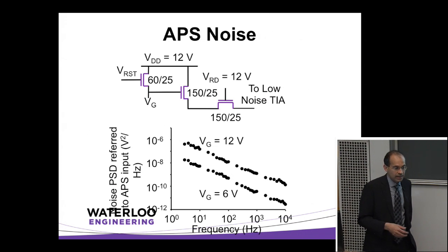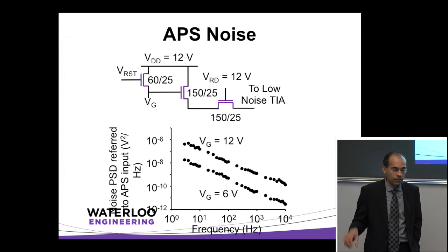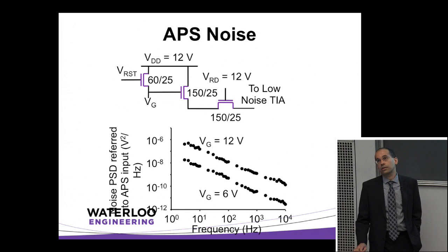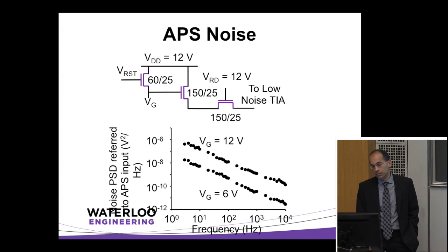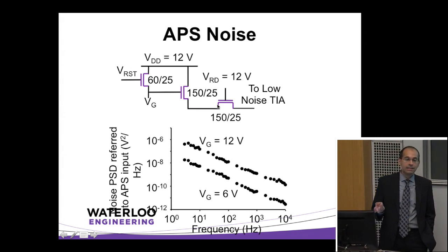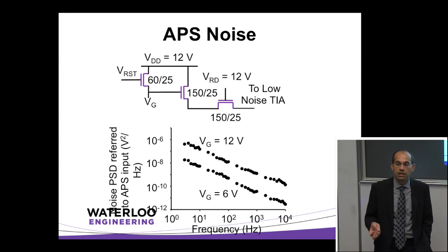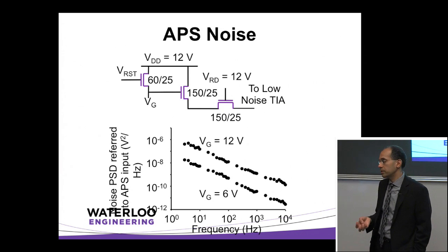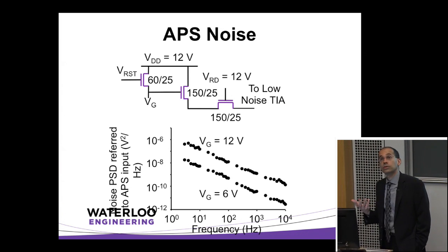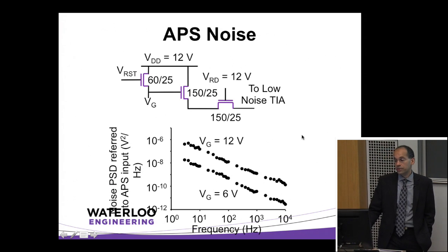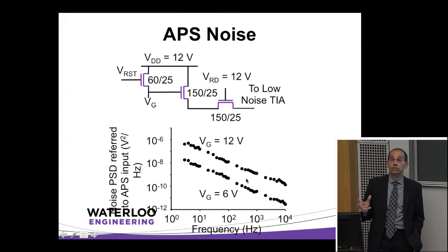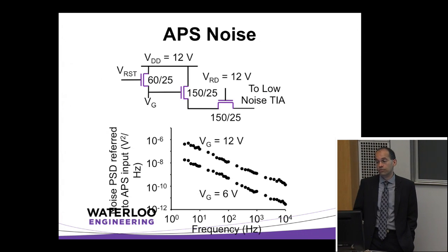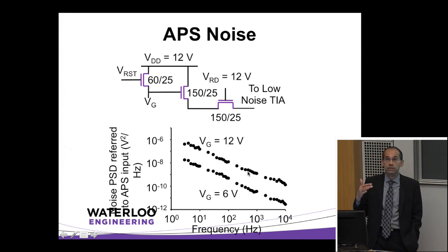Now, the last surprise that we had when we were trying to get these active pixels to fly was this random stochastic noise that I was talking about, right? Like random noise in the pixel. And what I mean by random noise is the classic noises that come with any kind of semiconductor device: the thermal noise, the shot noise, the 1/f or flicker noise. Those are to be expected. Okay? So flicker noise, for example, in a device made using an amorphous material is typically very high because the density of traps, the density of trap states, is very high. Thermal noise is not too bad, but the flicker is usually where the problem is.